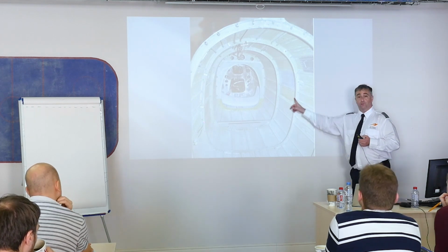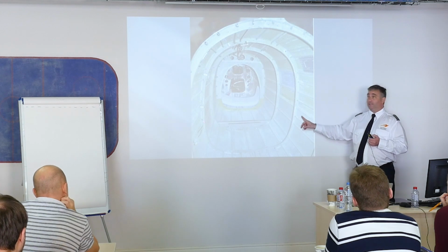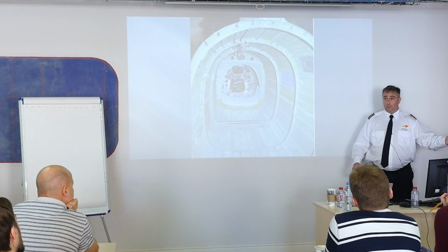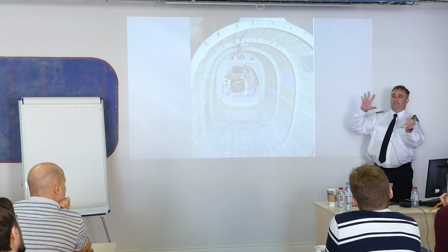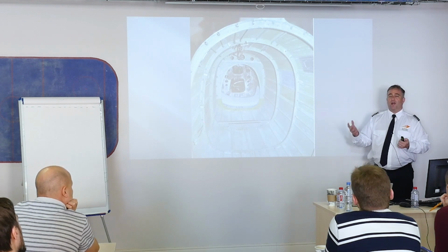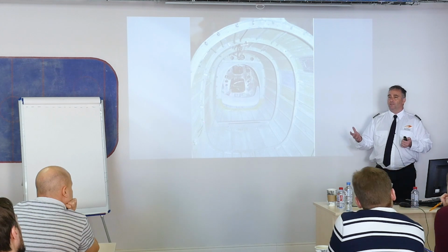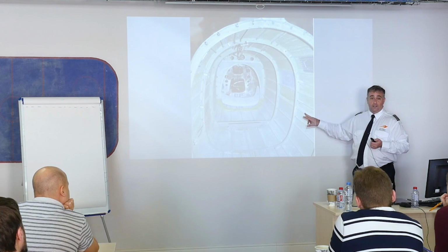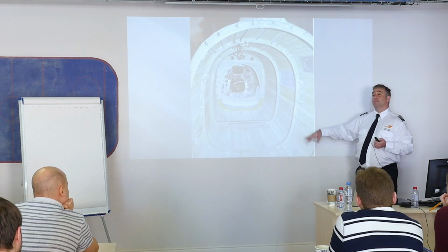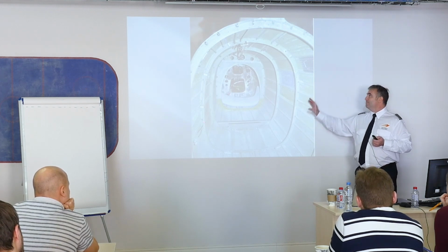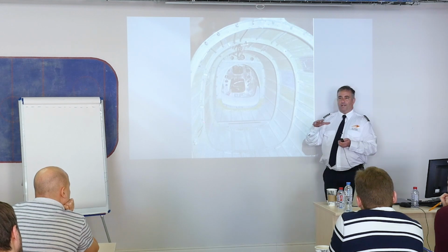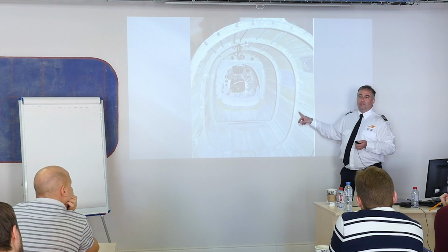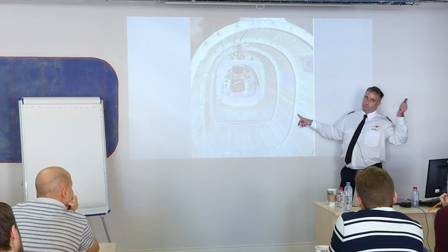It's built out of plastic, and it is a monocoque design airplane. So it does not have longerons and stringers. Instead, all it has is a rear bulkhead and a firewall. And all of the skin maintains the flight loads as we fly through the air, whereas here, they're shared by the longerons and the stringers. Okay? This is a very lightweight design, but